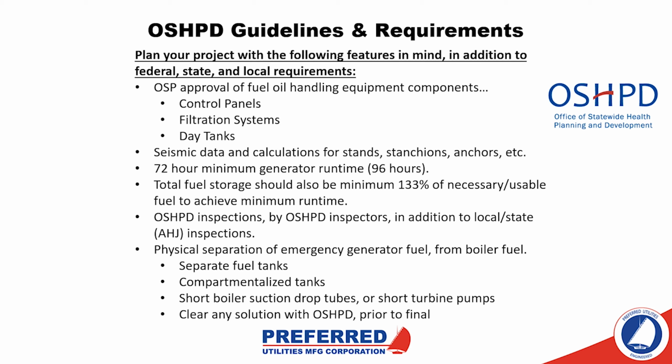And that fuel below it, and this is a very important part of this situation, that generator fuel available below it has to be enough to run the generators at their minimum runtime. So we can't just have short pumps. We have to make sure those pumps have enough height in their installation location so that the fuel below can run that minimum generator runtime. That can become a little tricky on retrofits.